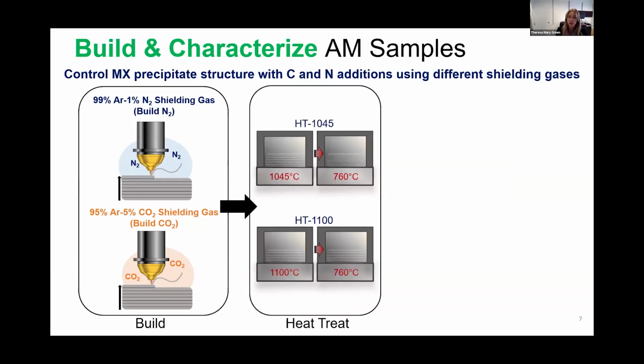So we also performed 2 different typical heat treatment processes called normalization and tempering, whereby samples were cut from the as printed specimens and they were heated at high temperatures for a set amount of time. And this was in order to remove residual stress that is incurred during the AM process itself, and also to produce equiaxed grains, which is better for isotropic mechanical properties.